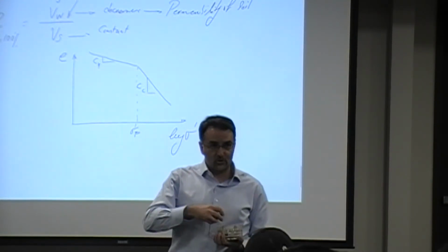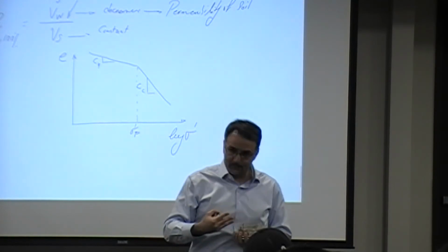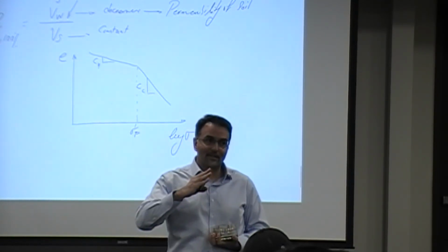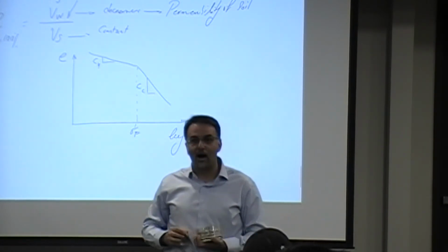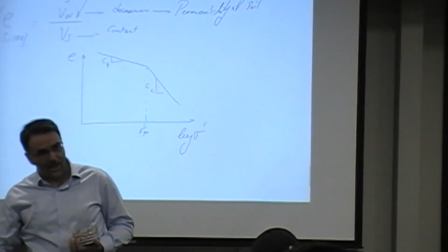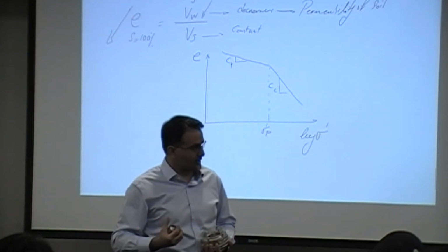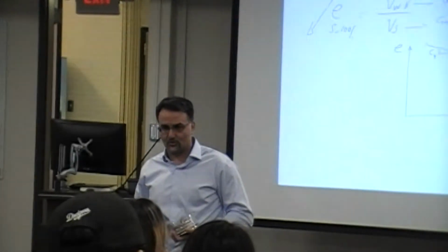That means that if you reduce the load, now the water gets into the body of the soil. Right? Now what happens? Void ratio increases, right? The volume of water would be going upwards. So we do it both for the loading and unloading, and we're going to talk about the behavior of the material, how it would look like, and how we can figure out what those parameters are.